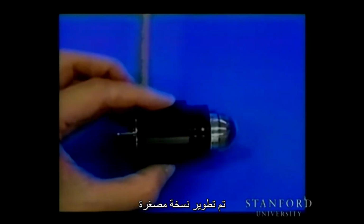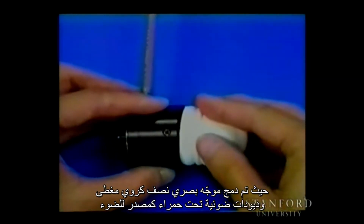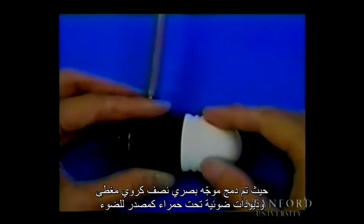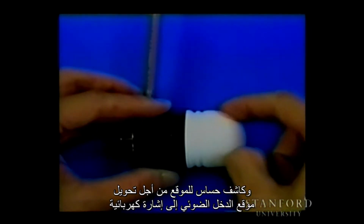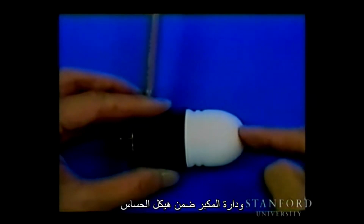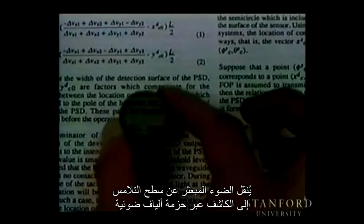To improve the size and the operational speed of the sensor, a miniaturized version was developed. The hemispherical waveguide with cover, the light source infrared LEDs, a position-sensitive detector for converting the location of the optical input into an electric signal, and the amplifier circuit were integrated in the sensor body. The scattered light arising at the point of contact is transmitted to the detector through a bundle of optical fibers.